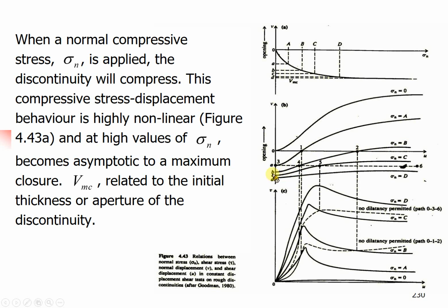It will be the same when the rocks start to have a shear displacement. The joints start to dilate. It goes up to 0.2, then the shear displacement goes to 0, and the normal displacement keeps increasing. But the increasing rate starts to decrease when the shear displacement is large enough. If you compare this and this, you can find this.